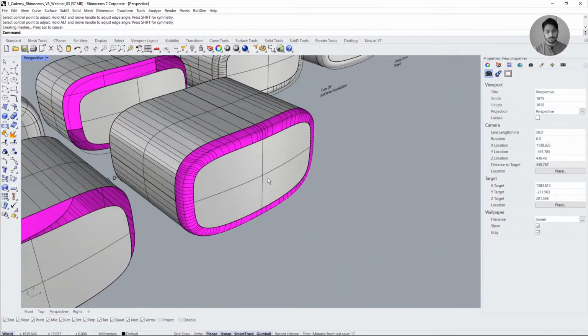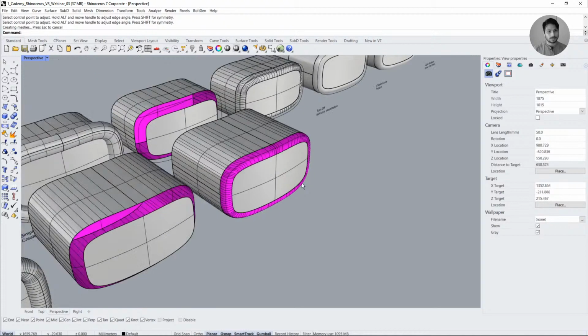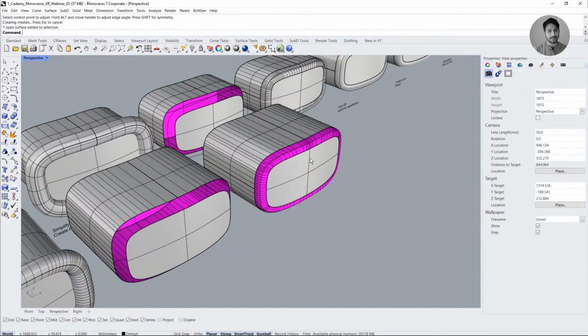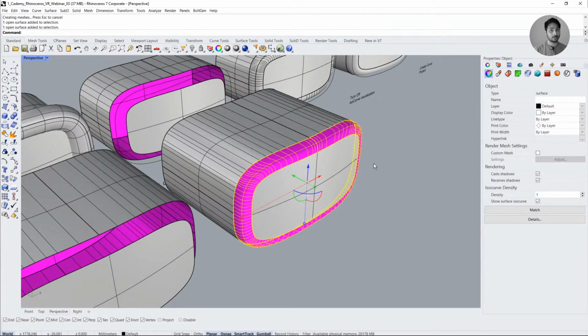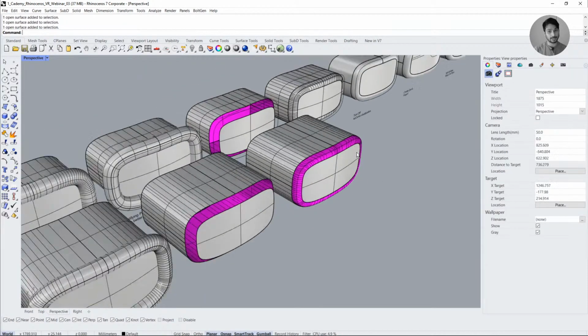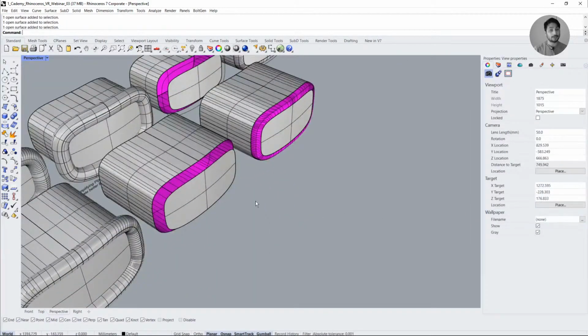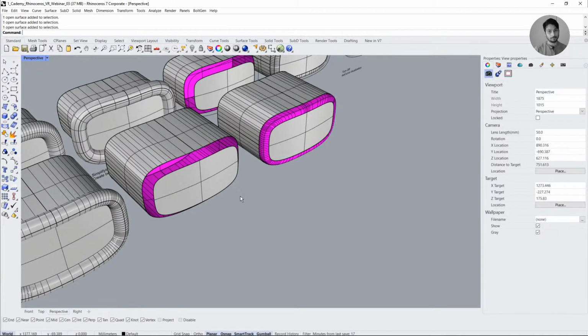Okay. You might wonder, some of you, why I have certain faces looking purple and certain faces looking white. Well, in NURBS or even in mesh, your face has a positive and negative side, and in general Rhino doesn't show you the positive and negative side in 2 different colors, but you can change these settings if you go to document properties. Let's see if it opens.